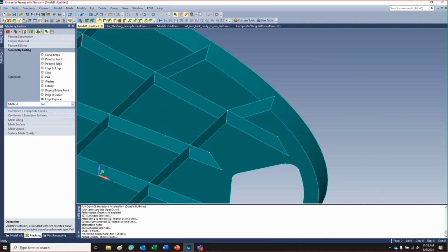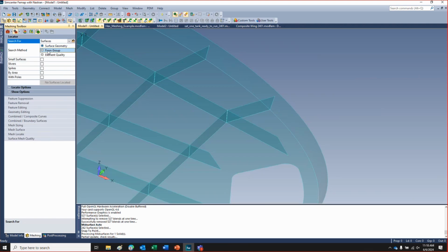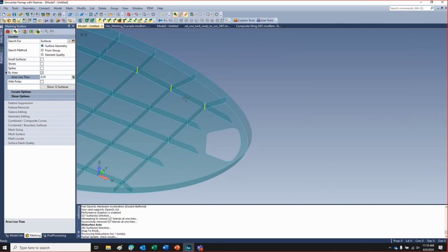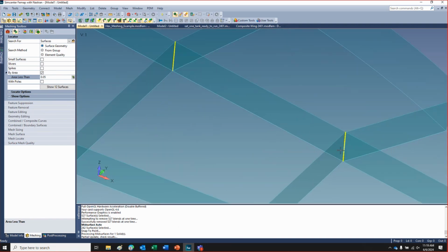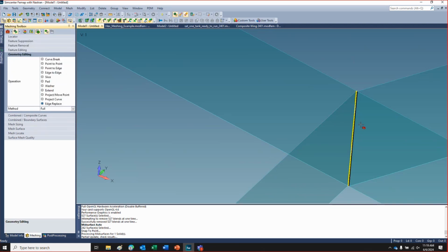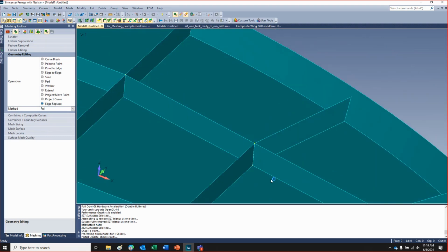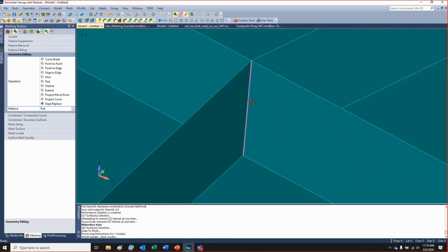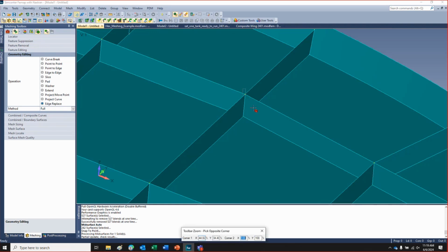Now, one of the things you can also do is come in here and do the toggle entity locator. So let's just say we wanted to find some small surfaces by area. Let's do 0.05, I think. Find me a bunch. Okay, that might have been too big. But essentially, what I can do is come in here and join all these little areas. What we're going to do moving forward is, we just had to get it implemented as a start. You could just go manually join things, but we're going to hopefully have a way to do some sort of auto find, auto join based on probably some sort of tolerance. Again, some of these are a little tough to find.